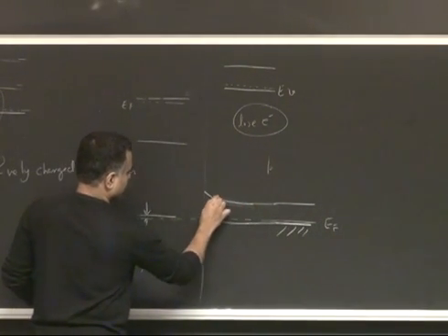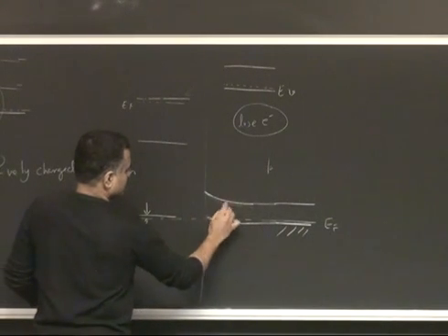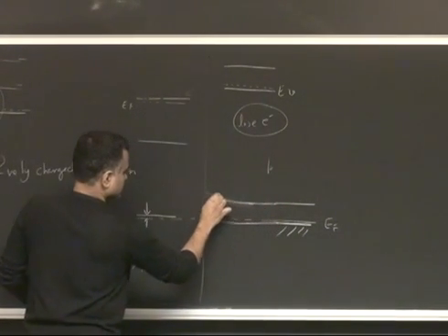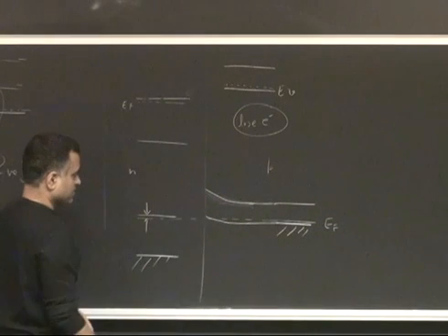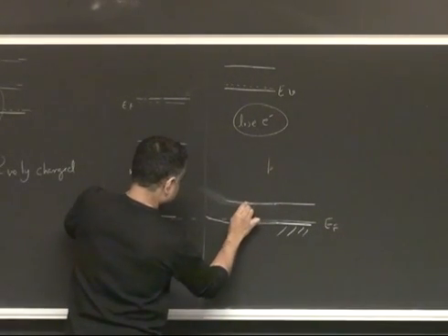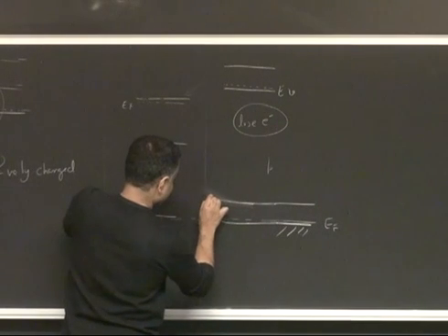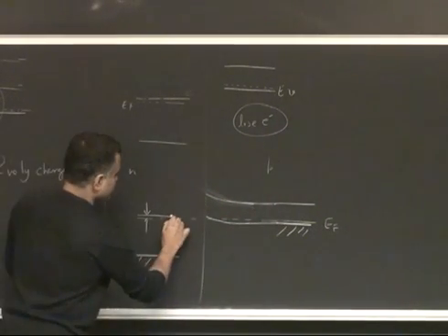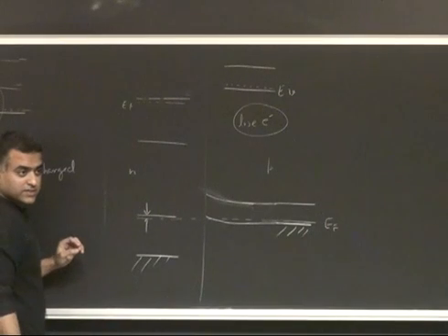And so the band diagram is going to look, remember the gap is not changing because of all this stuff. So the band gap is kind of locked to the semiconductor composition, right? So it's going to look, oh, sorry, I cannot, okay, something like that. Okay? It's going to just bend up. And on the left side, it's going to actually bend down. Right? Do you see that?